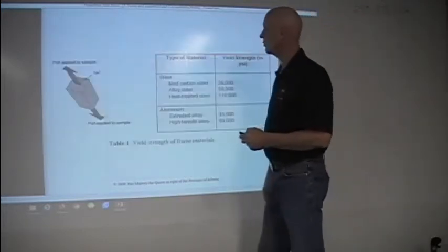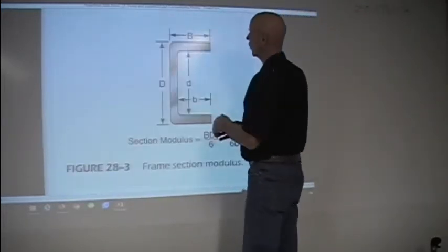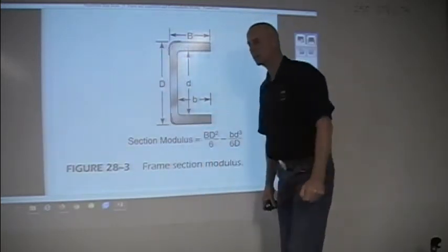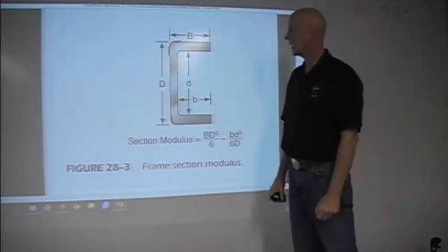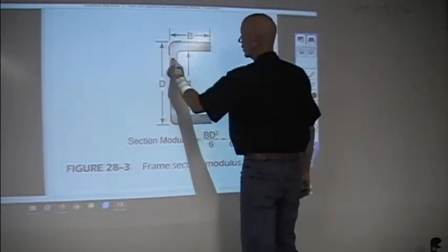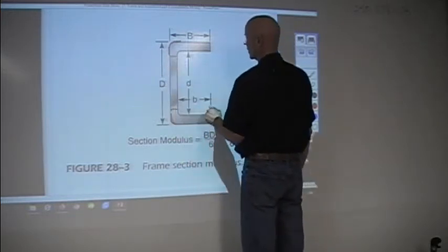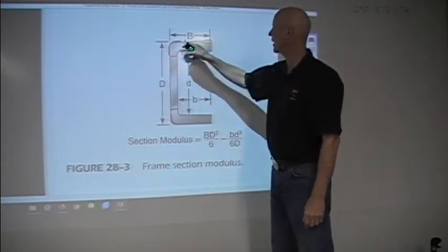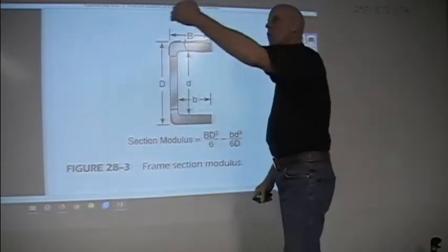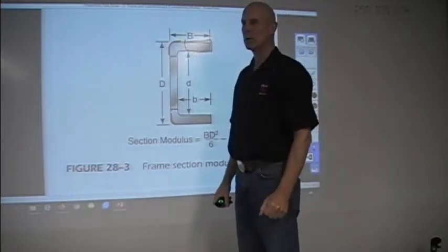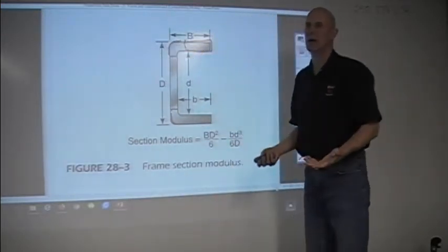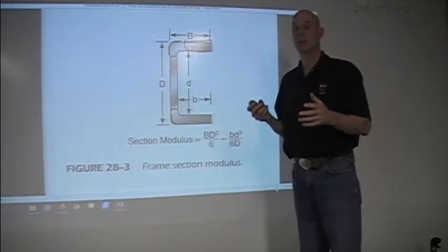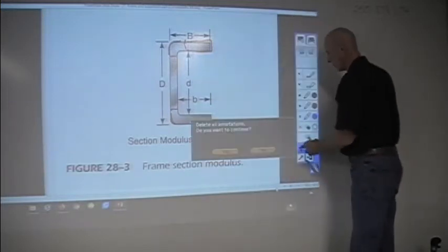So what that means is, if we go back and take a look, we do not want to do anything to this area in here. So no welding on that or drilling on that. If we're going to drill, it's going to be from this point to this point. Now the other thing is welding on the flange, anything in this area here. If it's before the front drive axles, no. But if it's after the drive axles, because that's not a load-bearing surface and it's not part of the structure, some of that you can. But be careful no matter when we're doing any welding or drilling.